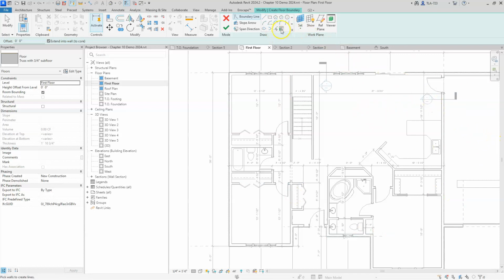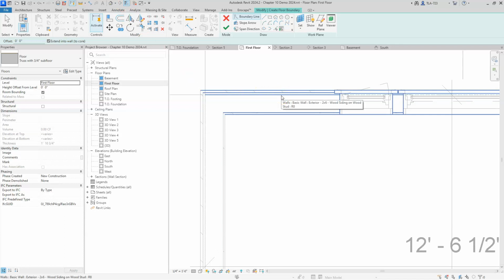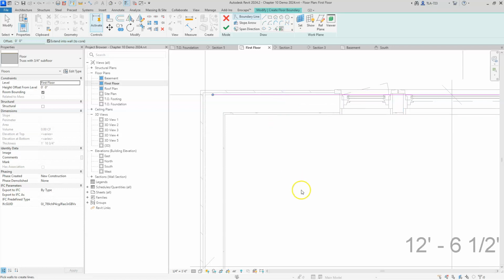I like to use, whenever I can, the Pick Walls tool. Unfortunately, sometimes it doesn't go to the correct portion of the wall, but if you watch carefully, and make sure you have thin lines enabled, you can get your cursor pretty close to that, and then when you click, you'll see where the magenta line shows up, and it did happen to hit the target this time.